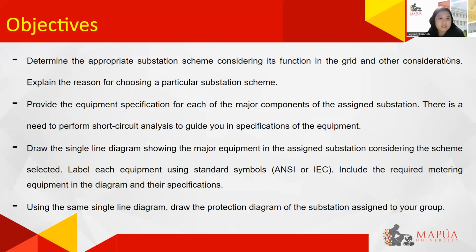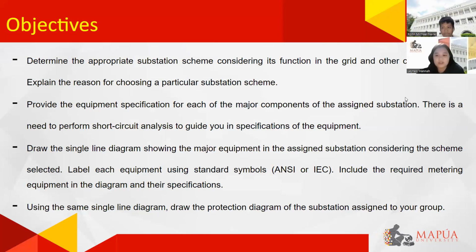and explain the reason for choosing a particular substation scheme. Then provide the equipment specification for each of the major components of the assigned substation. There is a need to perform short circuit analysis to guide you in specifications of the equipment.